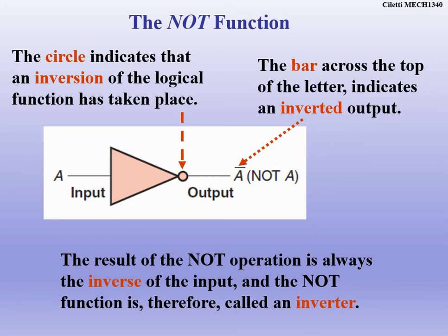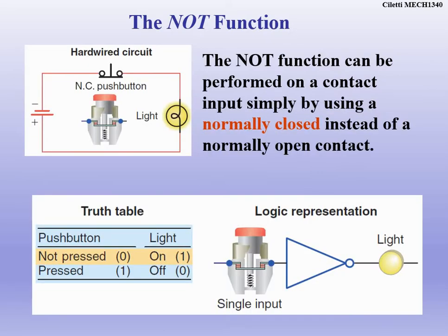Or a NOR gate. We would take an OR gate, put a bubble on it, okay, and it would make it a NOR gate. So that bubble is very significant, all right? Now, when you get into D flip-flops and things like that, the bubble means something, all right, whether we're inverting the signals or not. So anytime you see that little bubble, we're inverting the signal.